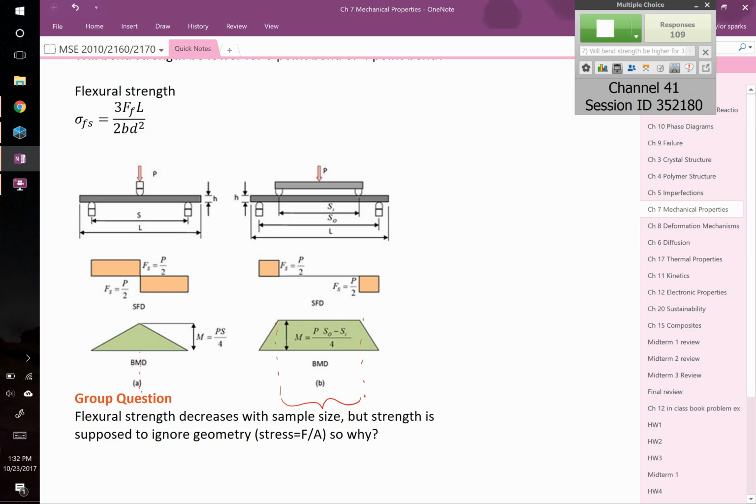Rosa? What exactly is a bending moment? So think of it like a torque arm. That's maybe a good way to think of it. It's a force multiplied by a distance. There's more to it than that, and if you haven't taken statics, don't worry about it. You don't need it for this class. In this class, you can think the bending moment is what causes rupture. The larger the bending moment, think of it like a higher stress that's locally present. Here, your stress ramps up, reaches a max, and then goes down. Here it ramps up quickly, stays at a max, and then goes down.